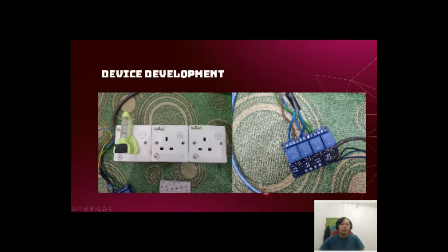The live wire will be going to the relay module where it will be split into 3. All 3 of the live wire will then go to COM, which means common, on each separate relay. After that, the 3 live wires will be connected to the NO, which is known as normally open, and go to each power plug.